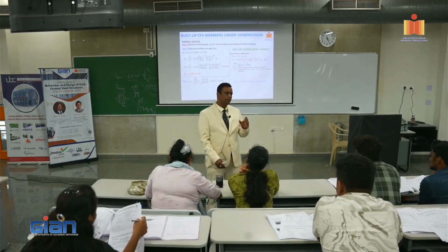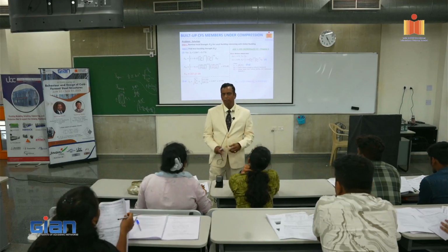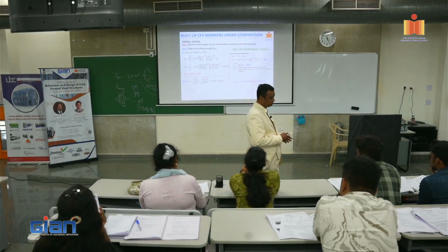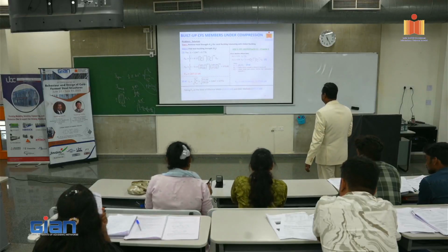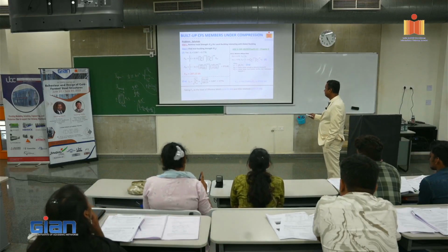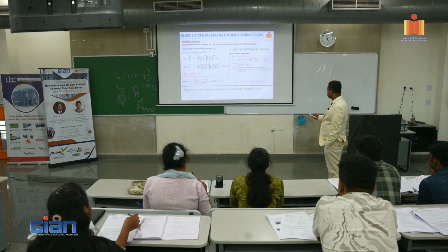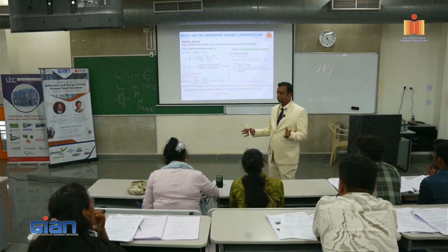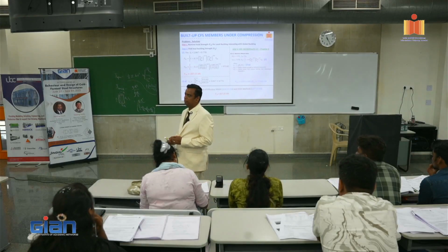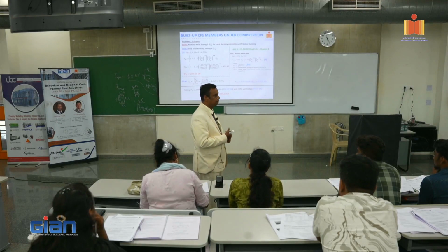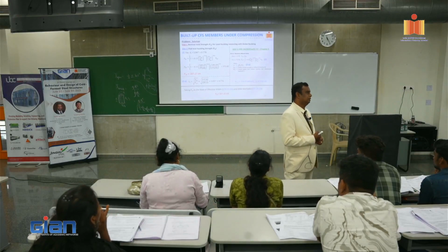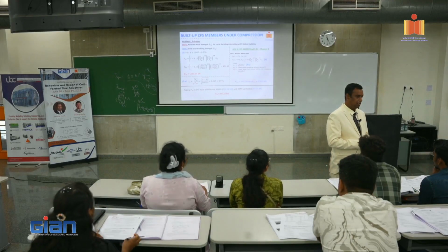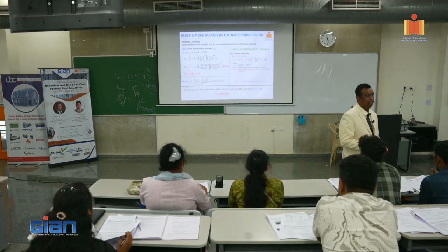No, because we have found Pnl using the direct strength method, using DSM. We need to find out the minimum of the two. So, using the effective width method 234, using DSM 207, the minimum is 207.25 Pnl. So now 2/3 of the problem is done. 1/3 of the problem was finding Pne. Don't use PCRE. Pne, now Pnl. What is remaining? Pnd. Right? So that's what we are going to do.